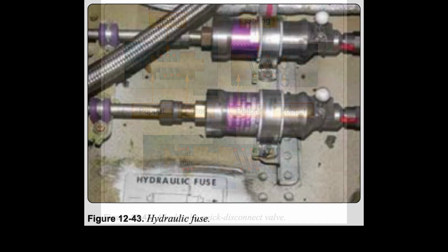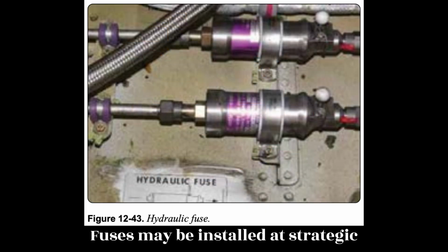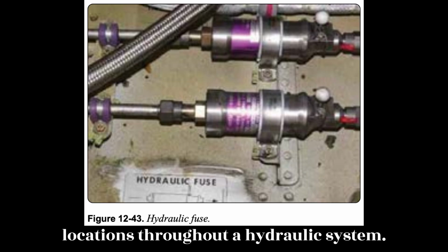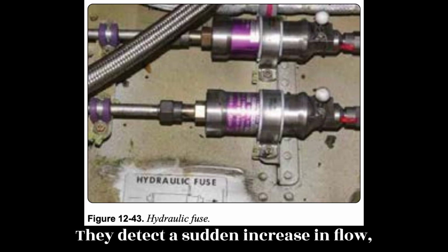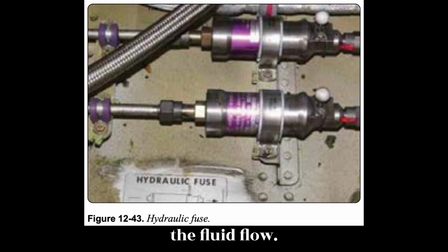Hydraulic fuses. A hydraulic fuse is a safety device. Fuses may be installed at strategic locations throughout a hydraulic system. They detect a sudden increase in flow, such as a burst downstream, and shut off the fluid flow.